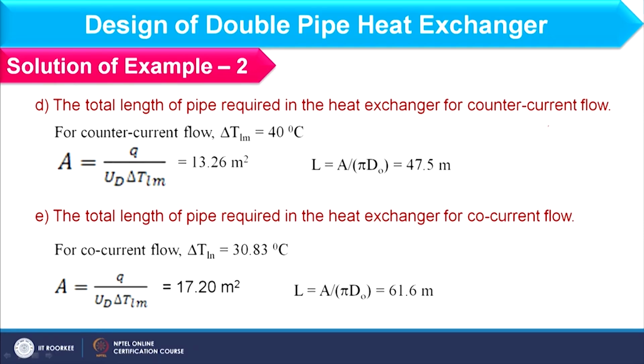So, here if I am considering counter current flow, this is the hot fluid which is moving down because it is reducing its temperature, and the cold fluid moves up because it is gaining heat and its temperature will increase, right. So, considering both temperatures, the hot fluid is moving from 100 to 70 degree Celsius, and the cold fluid is moving from 30 to 60 degree Celsius.